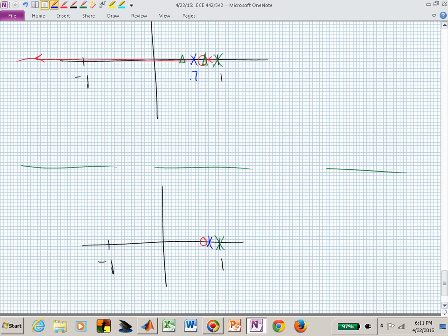Is it going to look much different when you step back and look at this from 10,000 feet? What's this root locus look like? Now you have 2 branches there, don't you, between 1 and 0.8, if that's where that blue X is. This one, I better be careful, is going right. This one is going left. They break away.